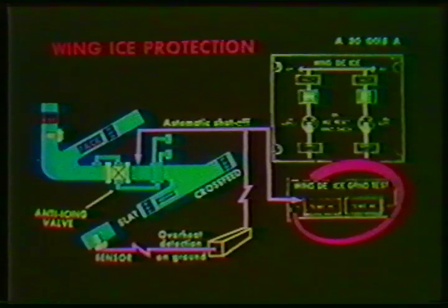On the ground with one engine running, operation of the system can be checked by setting the control switch to ground check. The switch will cause the engine high-pressure valve to close and the pack valves, if open, to close. This allows low-temperature air to be supplied to the wing de-ice system. If a predetermined temperature level is reached, the controller will automatically close the wing de-ice valve and illuminate a temperature high light on the second officer's panel.